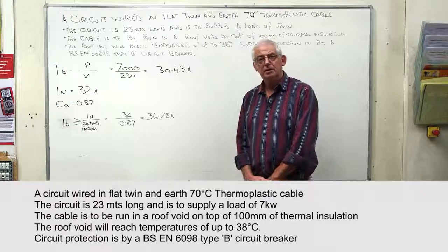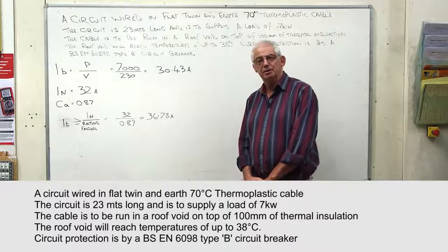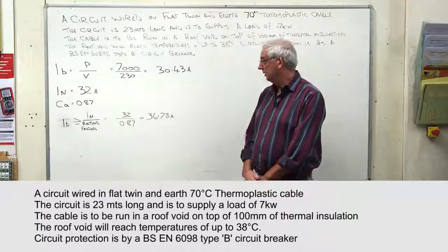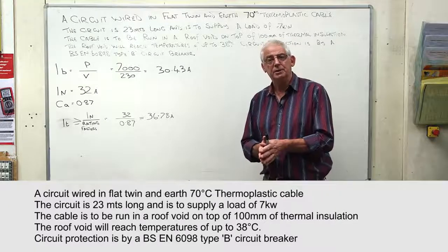Once we've found our rating factor, or factors, because often there's more than one that would affect the cable, we need to divide IN by the rating factor so that we can decide on the size of the cable that we need to use.